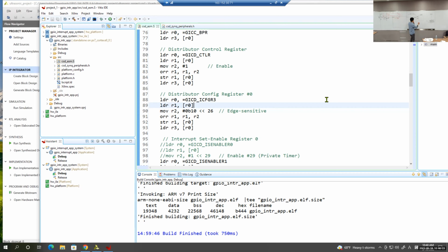So that means in the ISR you come back by writing to EOIR, you come back to the interrupted program, then another interrupt is generated because the line is still high. So your CPU jumps into the same ISR and comes back, but the line is still high, so it keeps doing this operation forever. Does it make sense?